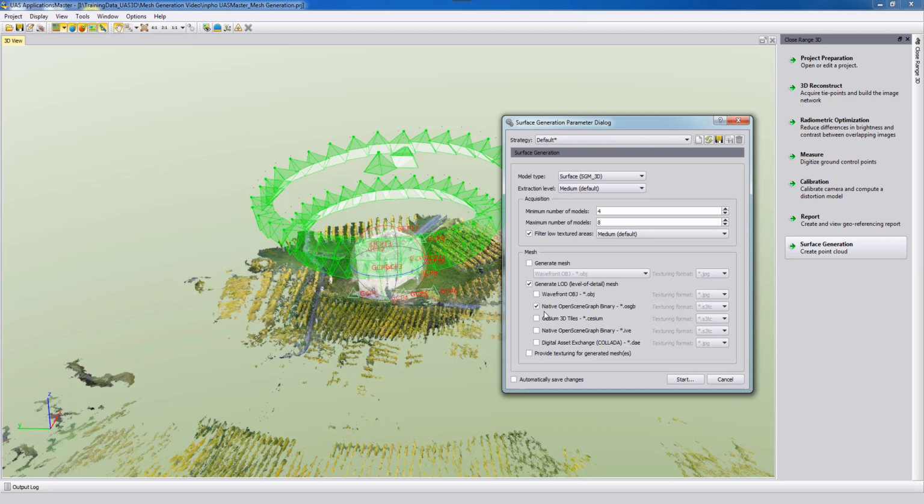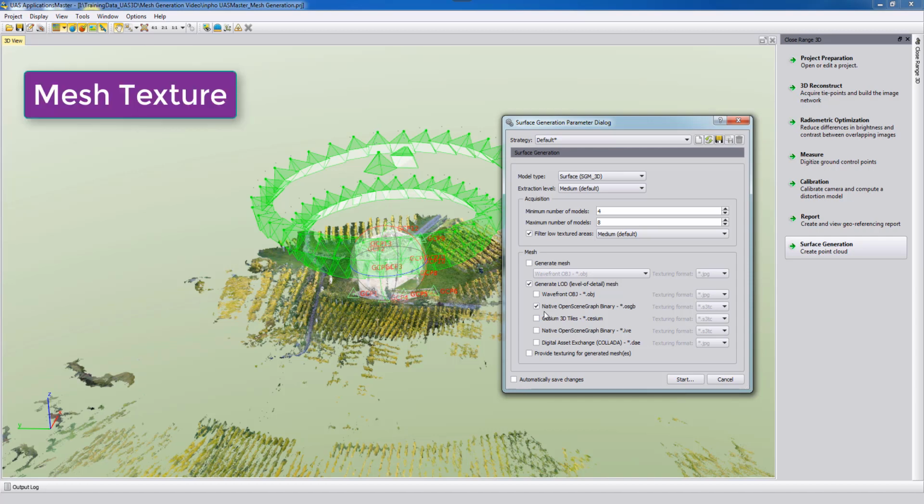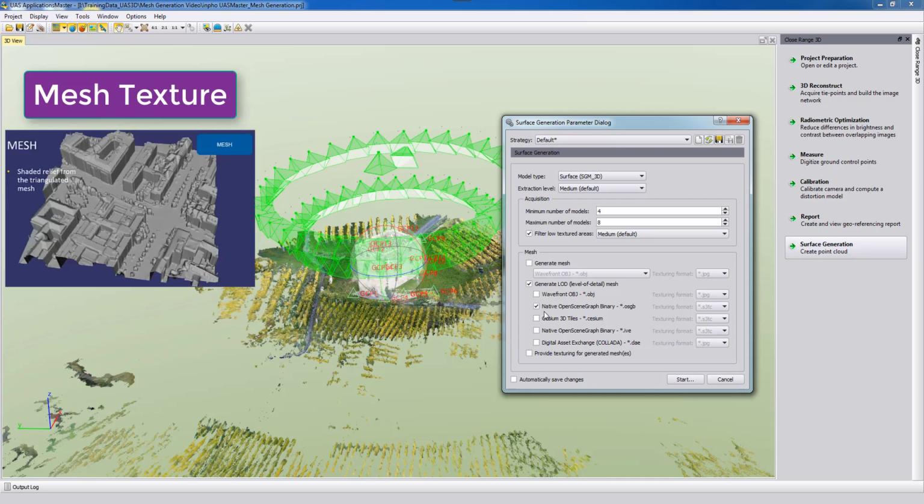The mesh itself, it's like a triangulated mesh, is not including the texture. At the beginning it's just extracting the mesh from the point cloud. There are some corrections done during the process to eliminate extreme errors, and also to remove some peaks, and also to look for when you have multiple models looking on one point, which one of the points fits the best for our point cloud, and then from the point cloud to the digital object model, to the DOM, and then from the DOM to the mesh.